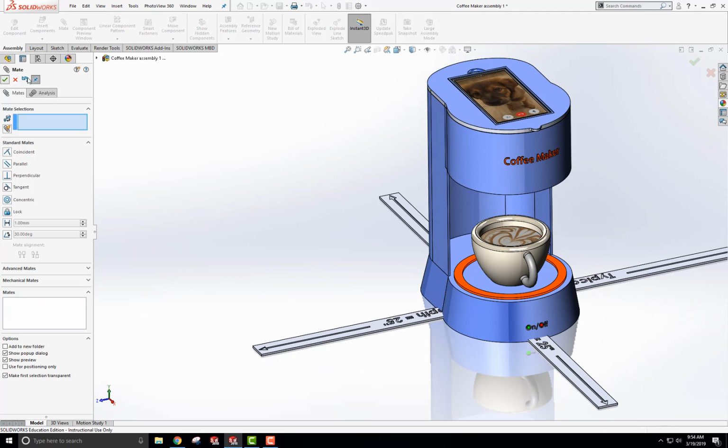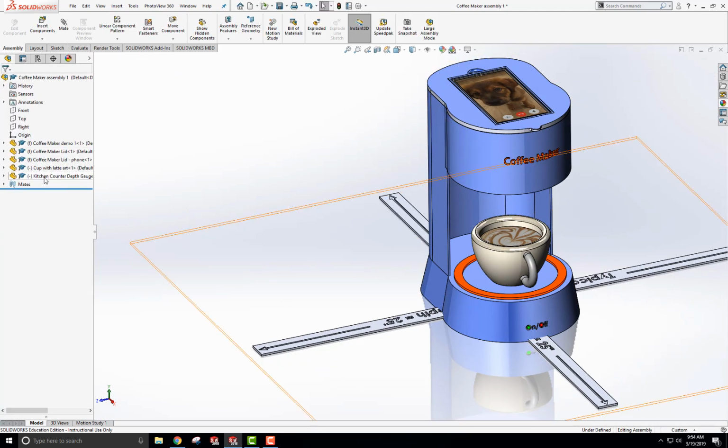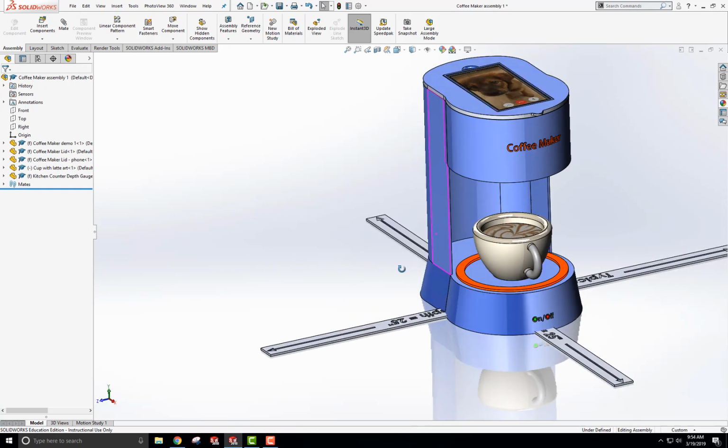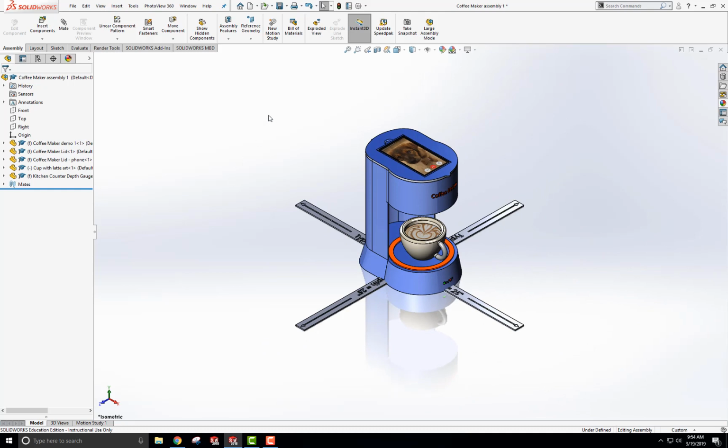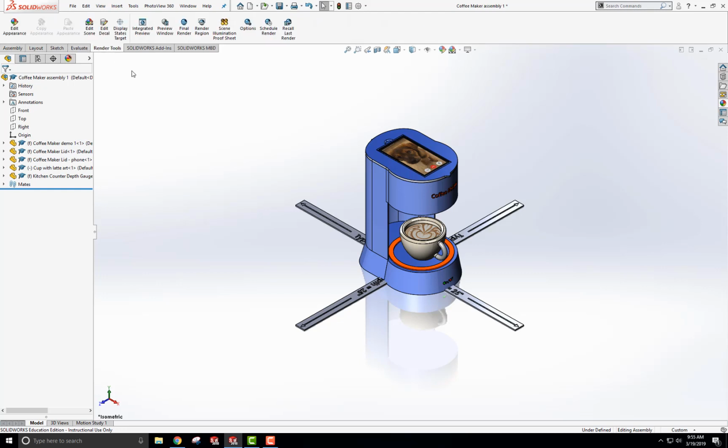And then what you can do is right-click on the depth gauge and fix it like this, so that it's fixed, so that it can't move around. Okay. Alright, I'm going to go Control 7 for isometric. Next thing is I want to bring in an image background, and I've already chosen the image offline that has good reflection on the surface for like a countertop. It's a general countertop image, and I have render tools up right here.